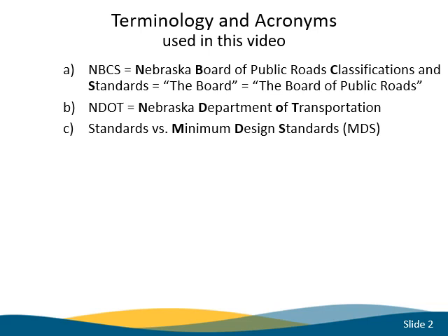MDS refers to the minimum design standards, which address only the design aspect of a work or project. Standards are often termed minimum, but realize there are maximums for super elevation and grade, and ranges for cross slopes. When we say minimum, sometimes it refers to all of those.